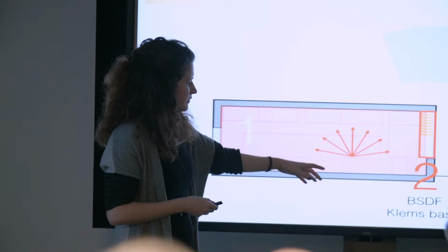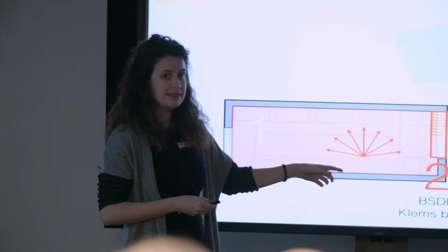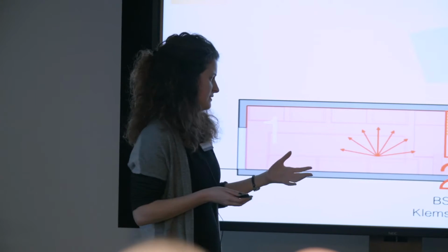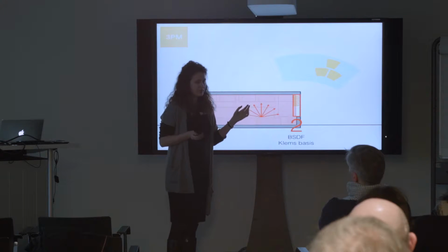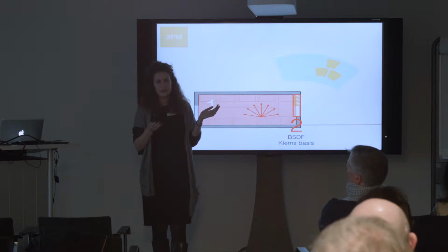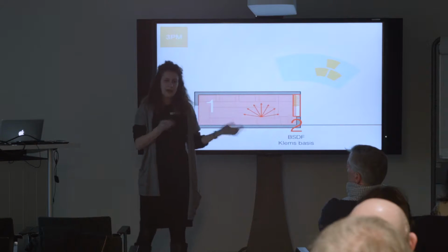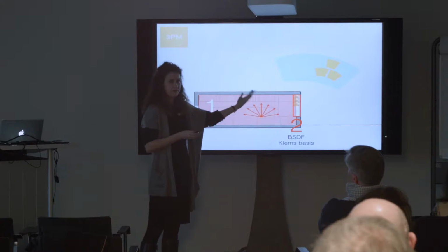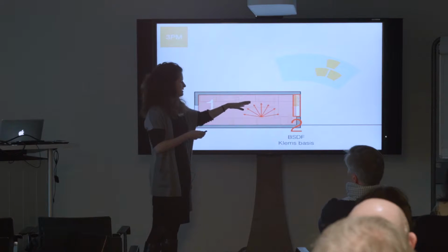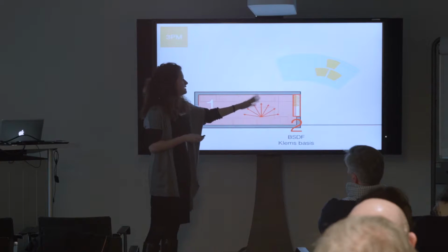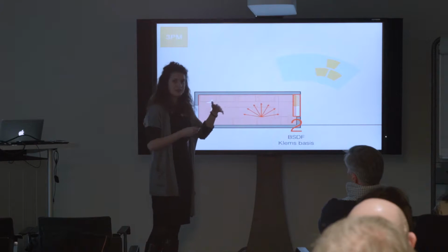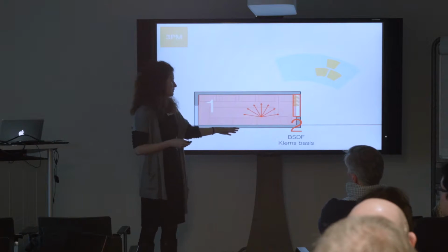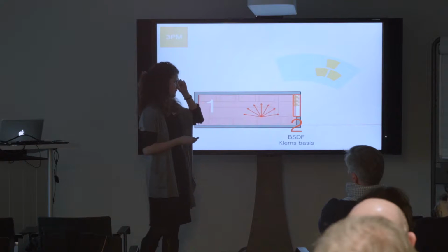Then at that point, we apply a BSDF material on the window, on the fenestration system, so that we have a correlation between the light flux that falls onto the window from the outside, so it's incident on the window, and the light that actually gets transmitted into the space or gets reflected off. And this is described in the BSDF that I'll show later.